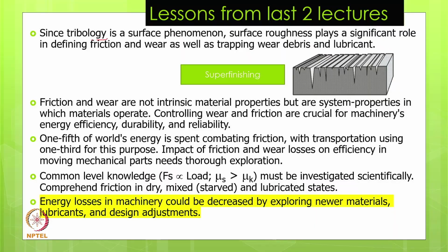It was mentioned that tribology is a surface phenomenon, and surface roughness plays a significant role in defining friction and wear, not only this, even in trapping the wear debris and acting as a lubricant reservoir. These are very important aspects, and this kind of ideal surface was shown. It has load bearing areas, and it has valleys to trap particles and to trap lubricant, or we say to keep as a lubricant reserve.